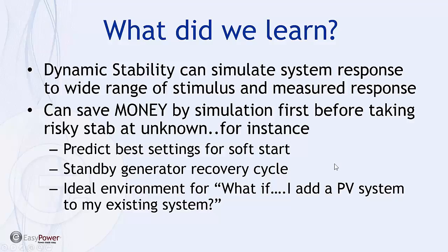So for instance, the applications might be just exactly this, predicting the best settings and the effect of running soft start settings before we apply those to large loads. Tune the generator or the standby generator's response to system faults. And obviously it becomes an ideal environment in dynamic stability for answering questions like, well, if I were going to take this system and now add alternative energy sources, what's going to happen in my system?